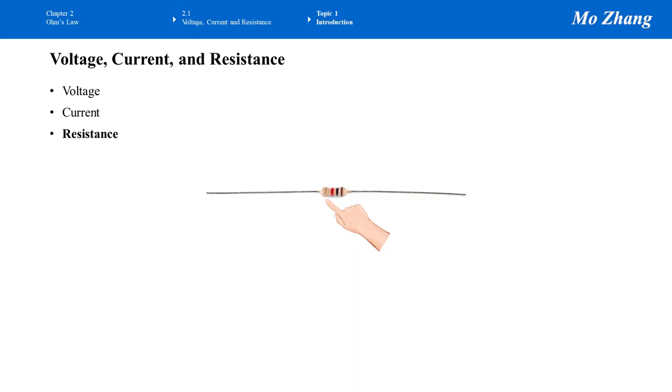The last color band, the color band all the way to the right, should be either gold or silver. So we flip this resistor. The 4th band is the gold band. The resistor is in the correct orientation. The first color band is brown, the second one is black, then we have red, and the last one is gold.